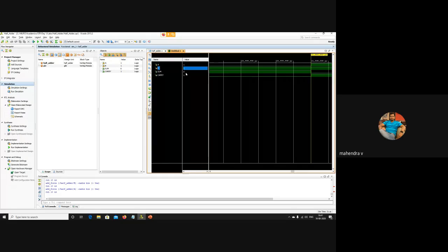Now we can say the half adder was designed using HDL, Verilog HDL, and then simulated, and functional verification was also done successfully. Simulation will happen anyway, but functional verification indicates the functional correctness of the system. Now it is acting as the half adder. How have we verified that this logic is satisfying our requirement? By giving various input patterns. Here we have given the inputs manually.